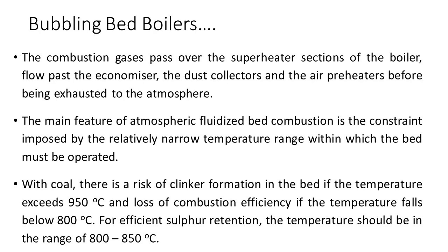The main feature of atmospheric fluidized bed combustion is the constraint imposed by the relatively narrow temperature range within which the bed must be operated. With coal, there is a risk of clinker formation in the bed if the temperature exceeds 950 degrees centigrade and loss of combustion efficiency if the temperature falls below 800 degrees centigrade. For efficient sulfur retention, the temperature should be in the range of 800 to 850 degrees centigrade.